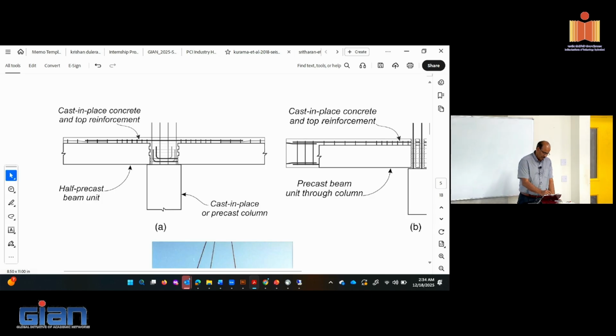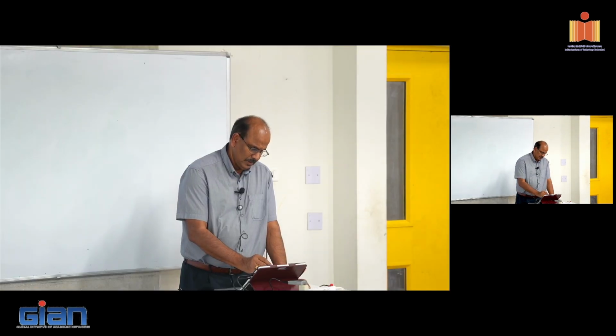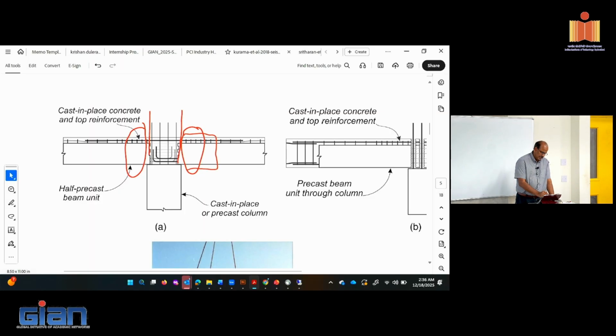If you imagine that the column is extending through here, as it's subjected to a lateral load, you would expect this region to experience maximum moment demand. So if it's cast in place, what's expected is that this region will develop a plastification, like the simple cantilever I explained yesterday with how the yield penetration takes place.